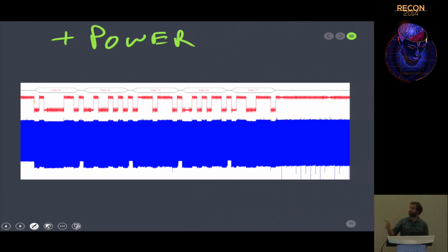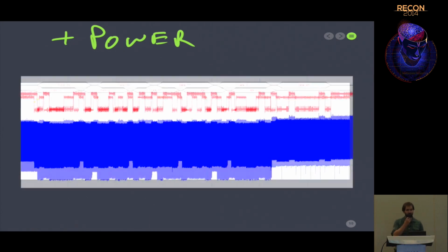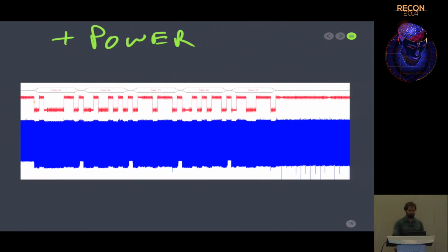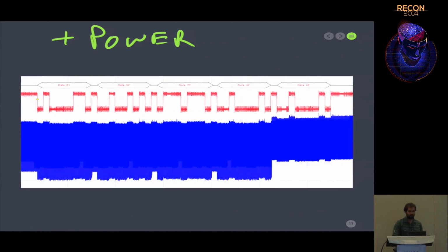And this is measuring the power as I put in the correct password, and then it goes off and does something else. Now, if I put in the wrong password, you see something very different. So what's happened here is, I guess you can see, this byte, I think, is wrong, or one of these becomes the wrong byte. And as soon as it's received it, so at this point in time here, it's finished receiving that byte, and it says, oh, spin into an infinite loop.